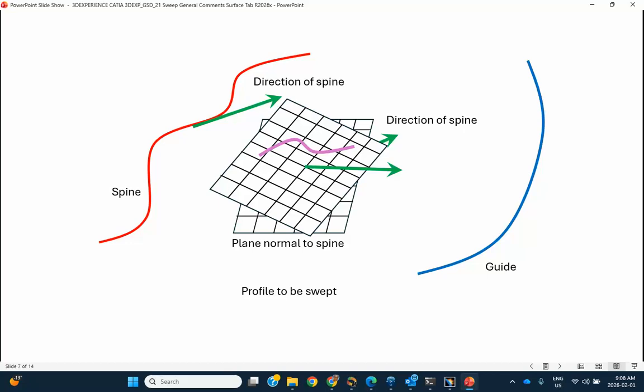Remember, with an explicit sweep, there are three subtypes. The subtypes were based on the surface and guide, based on the surface and two guides, and then a guide and a pulling direction. So this rigid body spinning or rotation about that green axis that's hidden here, see that green axis in the back? It is dictated, but which one of those three are you using?